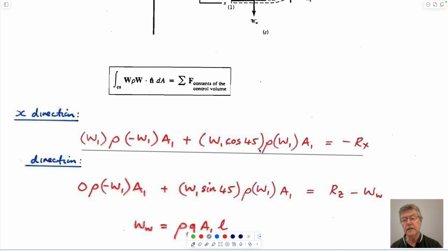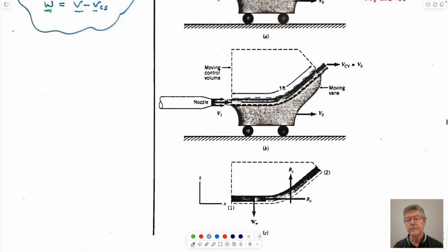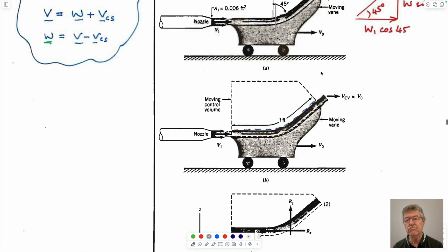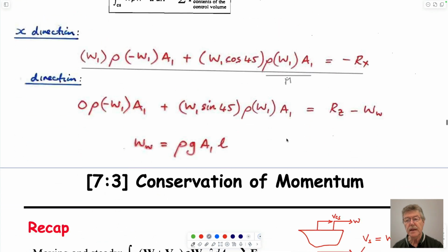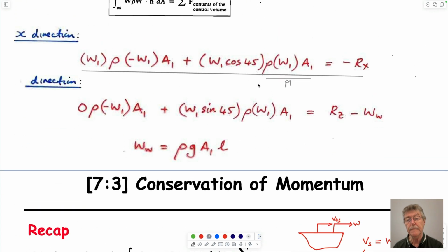And when it goes out, it goes out at a mass rate of flow, which is this. This is the cross-sectional area. This is the velocity as it goes out of the system. If the areas don't change, then it's the same velocity as it comes in, times density.